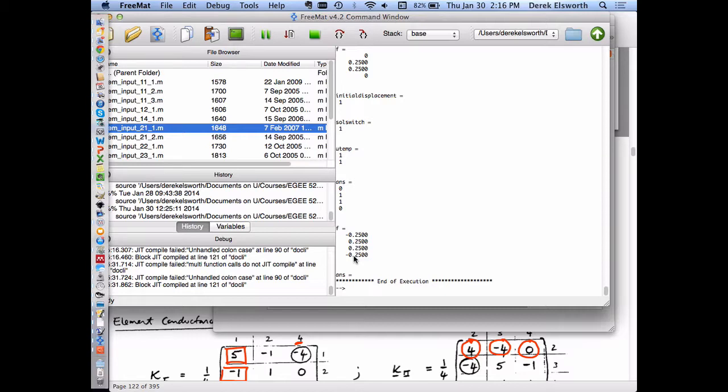So we've covered a lot today, but actually we've covered 10 years of finite element analysis. All of the techniques that are used here, or what are used in COMSOL, you'll never see them, they're embedded, but the mechanism is the same. And so you localize in an element, you describe local behavior, you take that local behavior and you index it so you can put it into this global conductance matrix. Once you have that, that's the main part. The other part you do is you code your boundary conditions in a certain way so that you can just manipulate the matrices. So I'll leave that. Exciting stuff, don't you think?